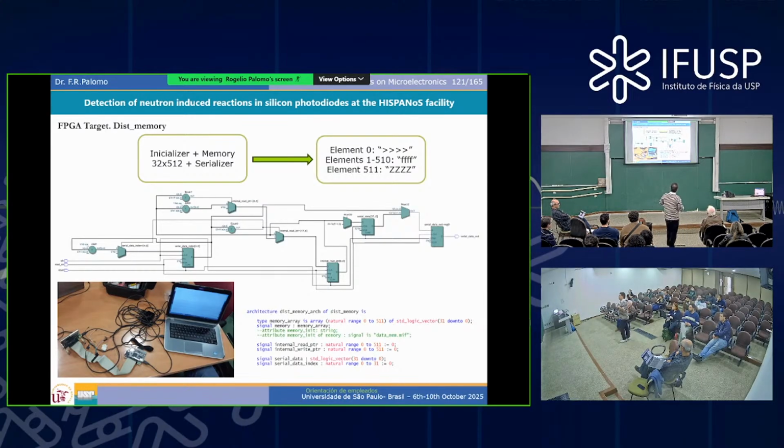a memory. The funny part, not from the nuclear physics but from the electronics, is that you don't declare a static RAM in HDL. It's implicit. So by default, the FPGA is routed to be an SRAM, and you have to discover that the hard way. So we learned a lot about the internal structure of the FPGA, which for sure you don't know from reading the manuals.